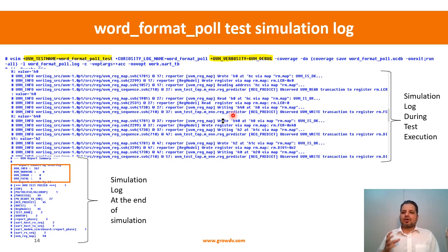So different components will log the information at different points of time, and with UVM all the logging format gets standardized. How it is getting standardized, what the format is, we will look at when we go deeper. But for now, understand that if we had put just a dollar display, then we wouldn't have any control saying from which file it is coming, which line it is coming from, what the ID source is for this particular message, and then the actual timestamp and the message, right?